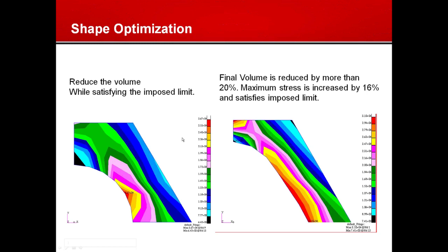And here in the shape optimization, the design variables you use are the grid movements. So you have to specify grid movements which can be combined into your final shape. So in this particular run, what we did was we extracted displacement patterns by applying loads at these interior grids.